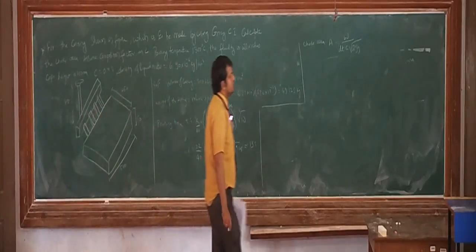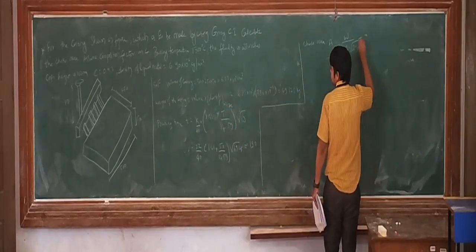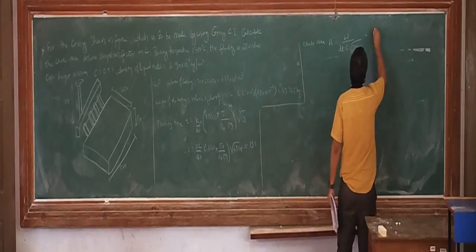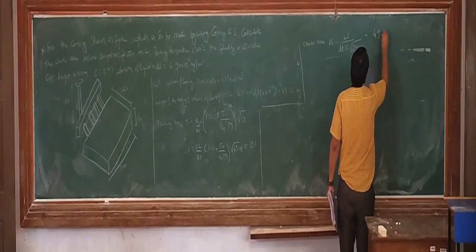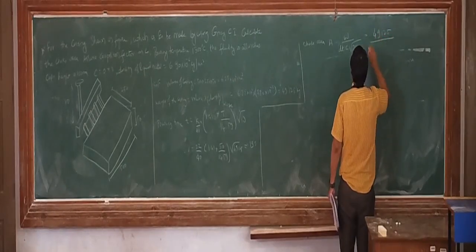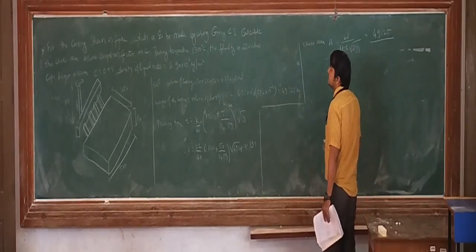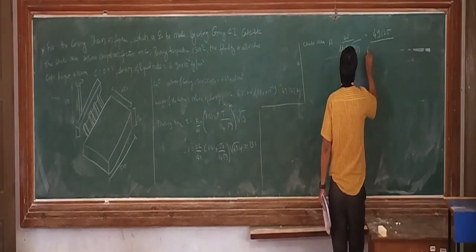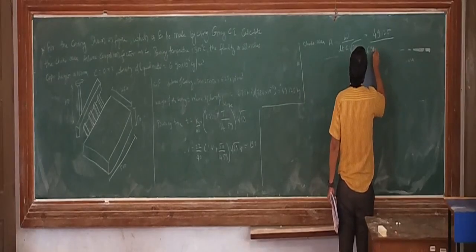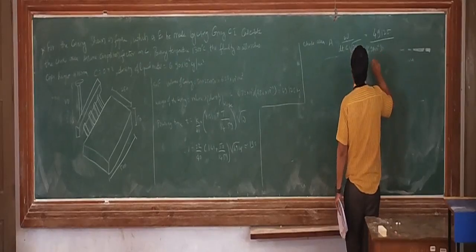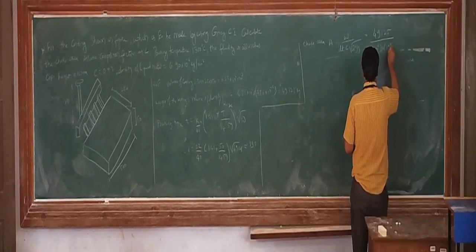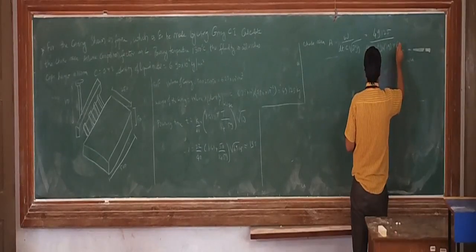So here W, weight of the casting, it is known, it is what we calculated, 49.125 kg divided by the molten metal density, that is 6.9 into 10 raised to minus 6, into pouring time is 19 seconds into C, efficiency factor, that is 0.73.